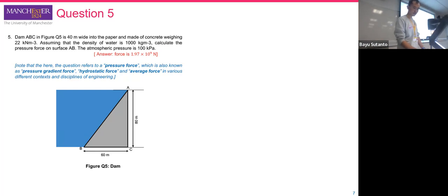This is the force at the center of gravity. And the height of the center of gravity, because this area is rectangular, is going to be half of the depth. So 80 is the total depth, and the center of gravity is half of the depth.